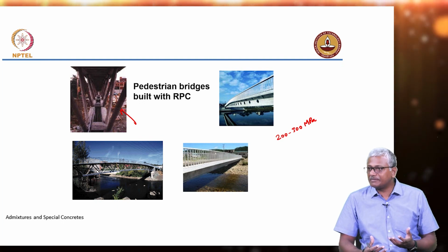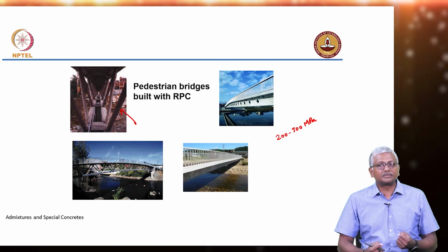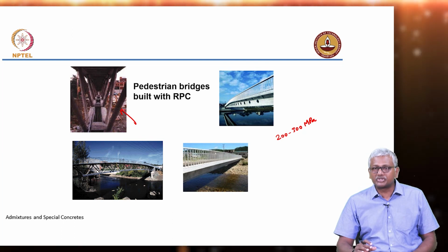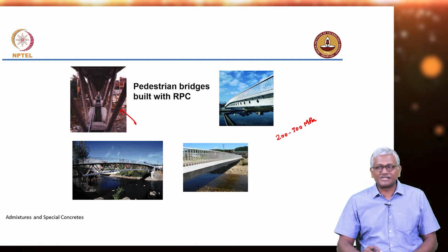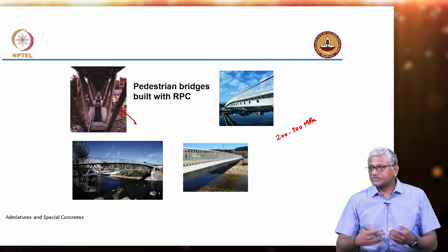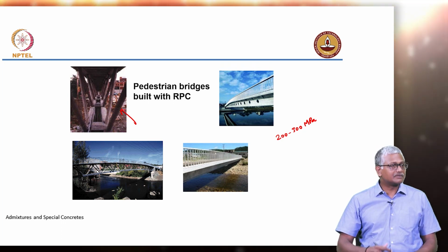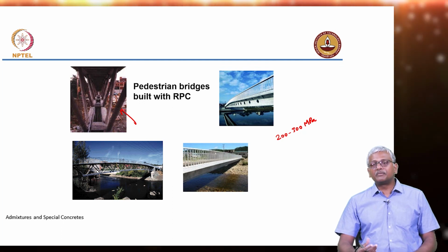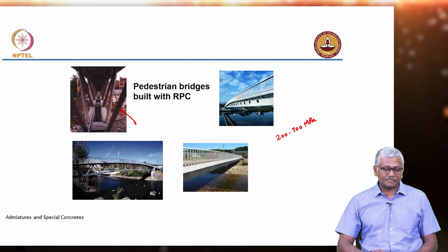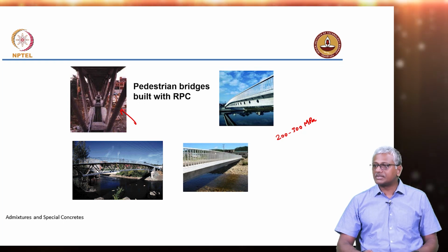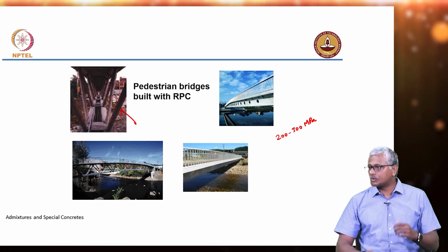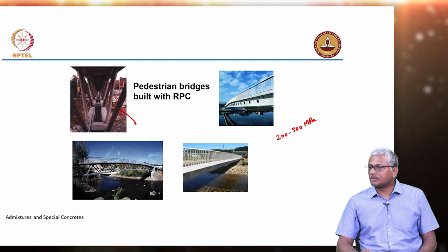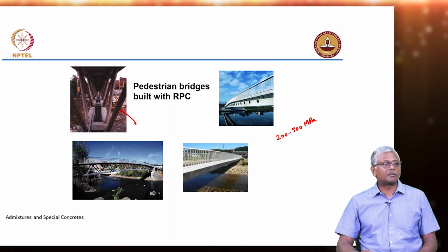Now, obviously, people are not brave enough to risk an entire roadway bridge without the use of reinforcing steel. So, it will take a long time before somebody can be convinced to use concrete with just fiber reinforcement even in members that are subjected to flexure. That will take some time. So, that is why these are all pedestrian bridges. You do not really have applications of actual roadway bridges, right. But post tension bridges, why not? You can definitely do it. There is no problem at all.